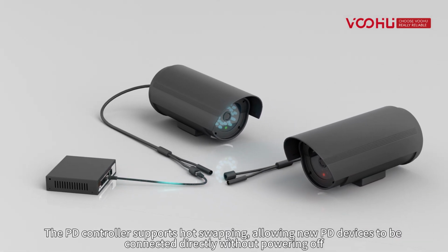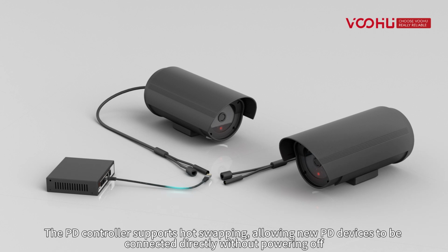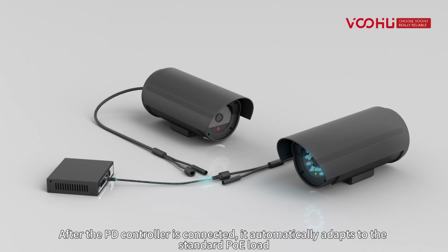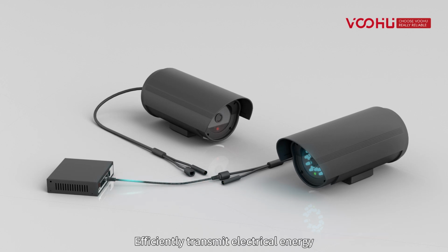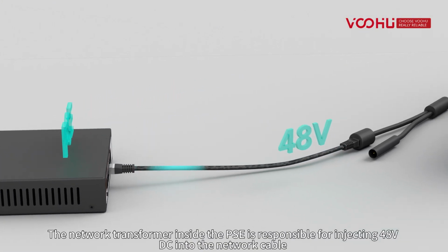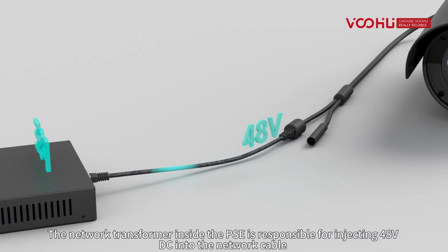The PD controller supports hot swapping, allowing new PD devices to be connected directly without powering off. After the PD controller is connected, it automatically adapts to the standard PoE load and efficiently transmits electrical energy. When powered by PoE, the network transformer inside the PSE is responsible for injecting 48 volts